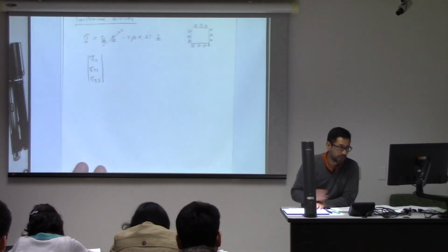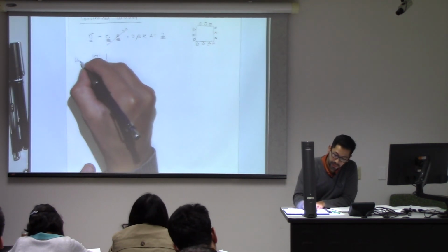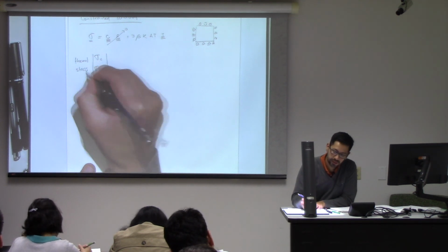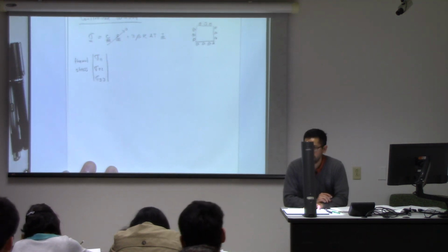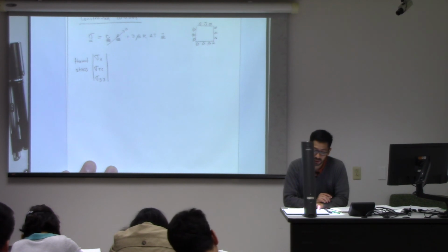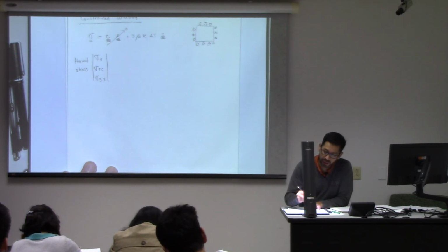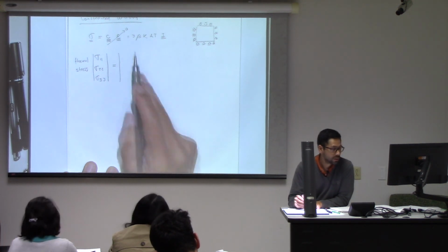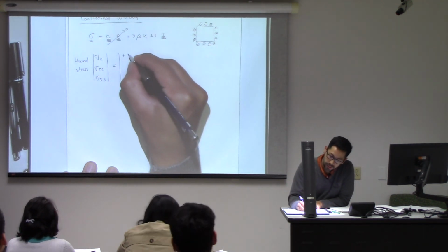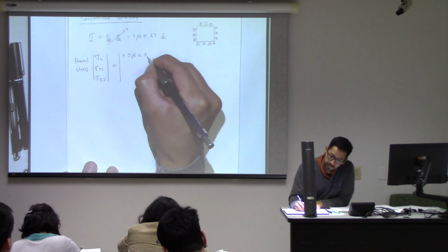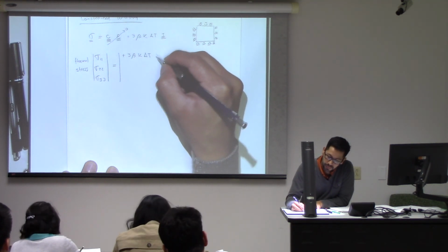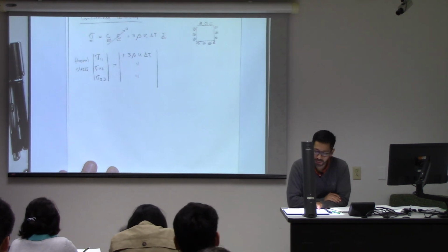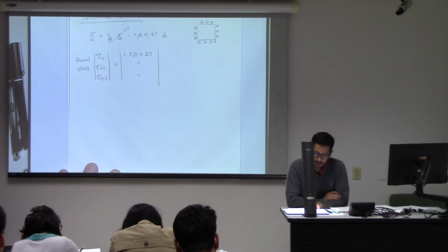Now, what do we get? We get a thermal stress, or, if you increase the temperature, it will be a swelling stress. And its value is straightforward from this equation. It's just 3 beta k delta t. Again, we don't have shear strain terms, so I'm not going to write those.